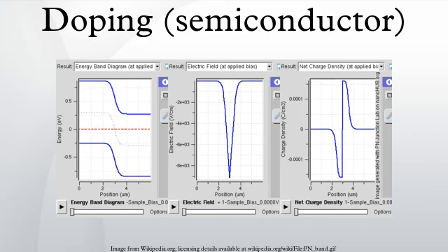In semiconductor production, doping intentionally introduces impurities into an extremely pure semiconductor for the purpose of modulating its electrical properties. The impurities are dependent upon the type of semiconductor. Lightly and moderately doped semiconductors are referred to as extrinsic. A semiconductor doped to such high levels that it acts more like a conductor than a semiconductor is referred to as degenerate. In the context of phosphors and scintillators, doping is better known as activation.